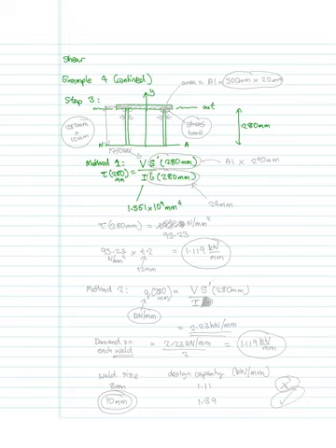Our V is going to be 1750 kilonewtons. Our B is going to be the breadth at 280 millimeters up, measured up. Since we're talking about stresses, it's again going to be our T2 plus T2, so that value there is going to be 24 millimeters.